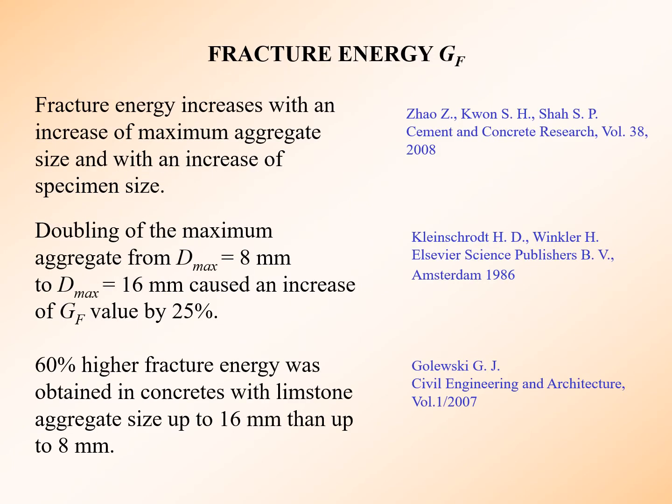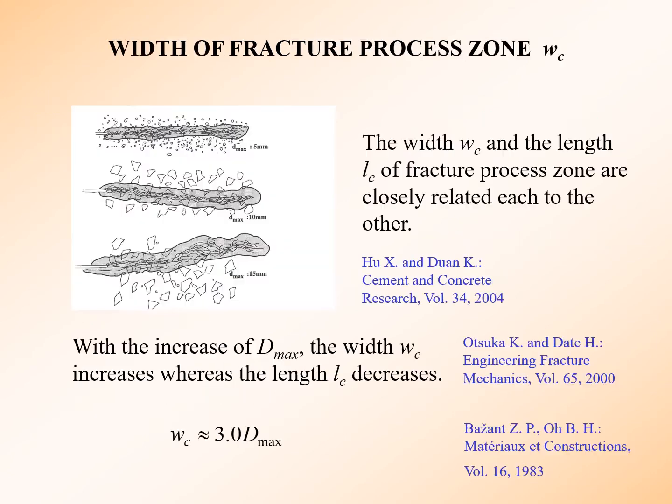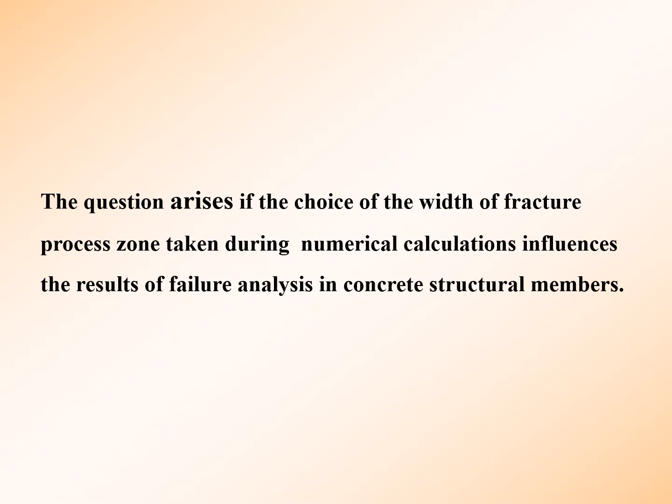We know that fracture energy increases with an increase of maximum aggregate size, but there are no consistent conclusions if aggregate size influences the width of fracture process zone. The question arises how to take the width of fracture process zone in numerical calculation.